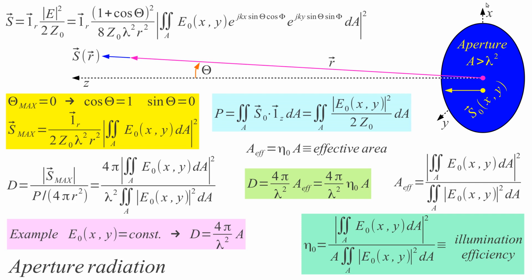This aperture could also be an aperture of a horn, of a waveguide horn. Which currents do I have to count there? That's a very difficult problem to be solved. So the best thing here is to use the Huygens principle and replace all sources, replace the field on this aperture, with sources that are built on this area, and these are called Huygens sources.